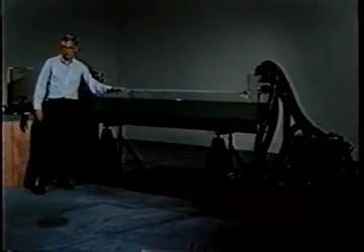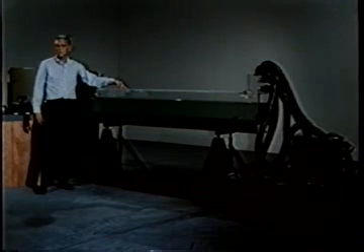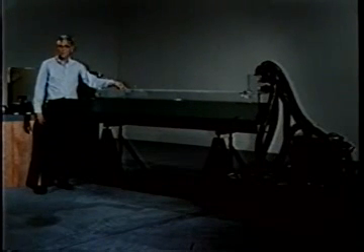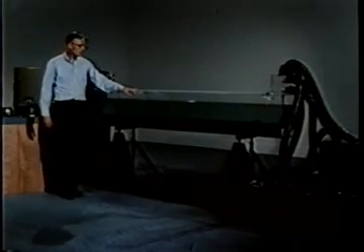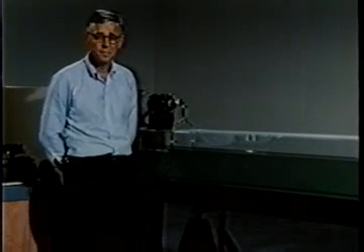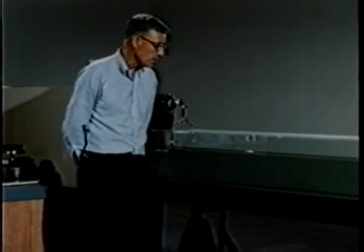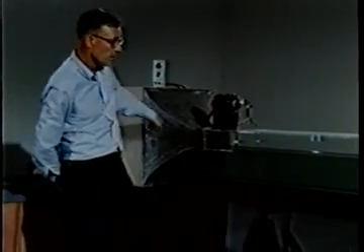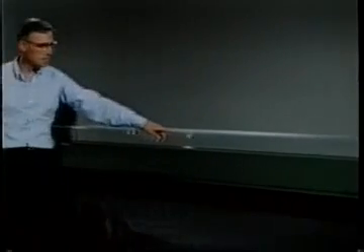Using this wind tunnel, we shall examine one flow instability in more detail, show its critical condition, and attempt to extract some more of the general features of flow instability. Air blowing over a liquid surface often excites waves. This is a flow instability. In this tunnel, we blow air over a mixture of glycerin and water. Room air enters the tunnel, flows through the test section, and is sucked out by these vacuum cleaners.